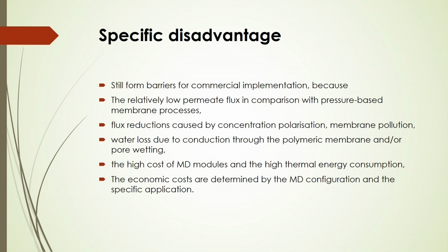And also there are specific disadvantages that still form barriers for commercial implementation, because in this case there is relatively low permeate flux in comparison with pressure-based membrane processes, flux reductions caused by concentration polarization, membrane pollution, water loss due to conduction through the polymeric membrane, and poor wetting.